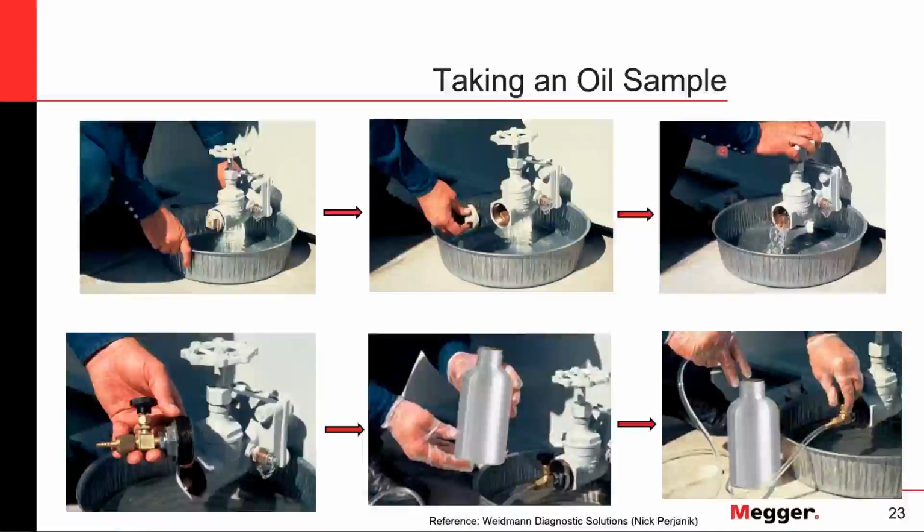After you remove the cap, be ready with lint-free paper or lint-free cloths to clean the area you just exposed, the internal thread of the valve. Make sure it's free of solid contaminant. Make sure you remove all the sealant residue that might be in there, any moisture. Make sure it's clean, and again, use a lint-free cloth.